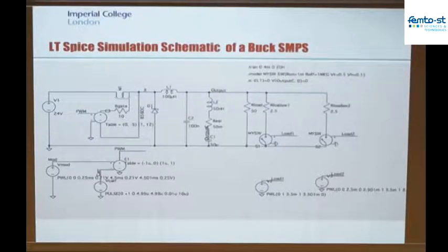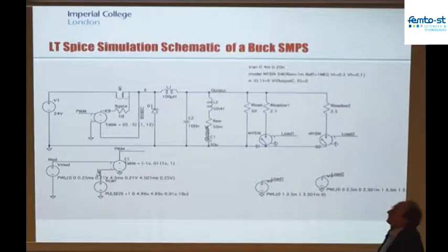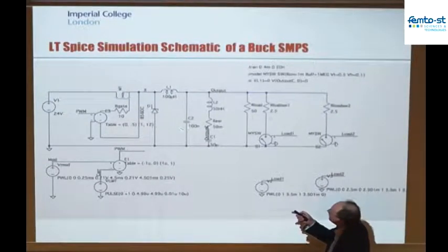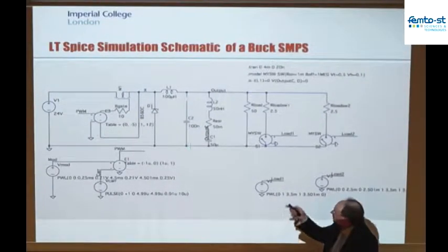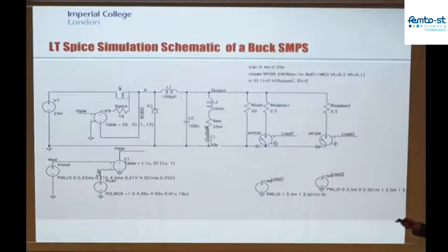One of the other things you notice is that there are two different capacitors here. From a practical perspective, once you start building electronics, even building power electronics for energy harvesters, you have to be very careful about this. There's a high frequency capacitor here, 100 nanofarads, which looks pretty well like just a capacitor. But there's another capacitance here, 50 micro, much bigger, probably electrolytic in nature. This one may be a ceramic capacitor. This is probably electrolytic.